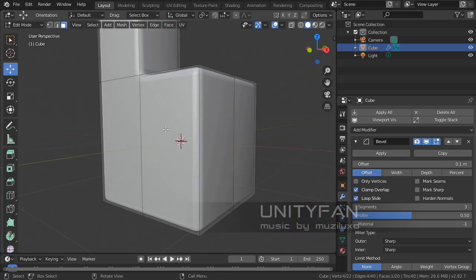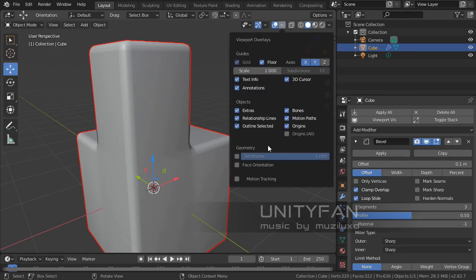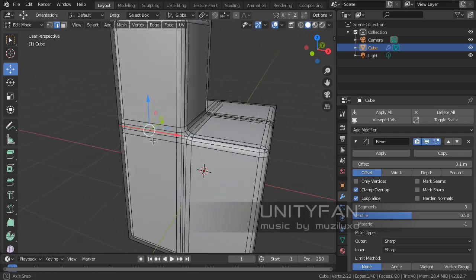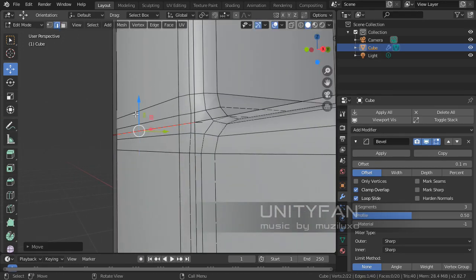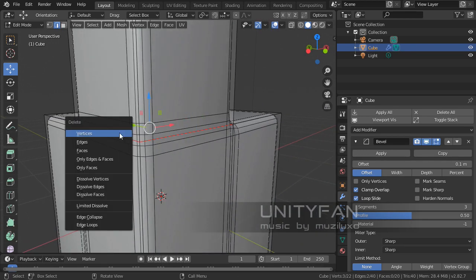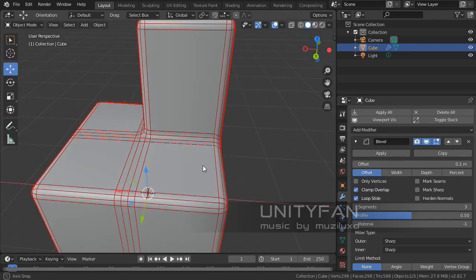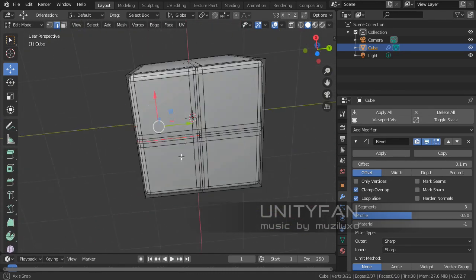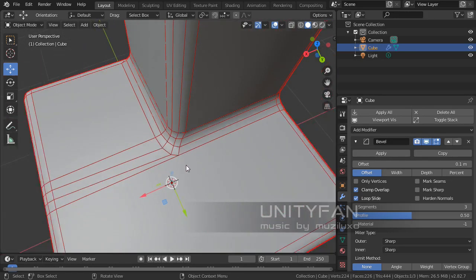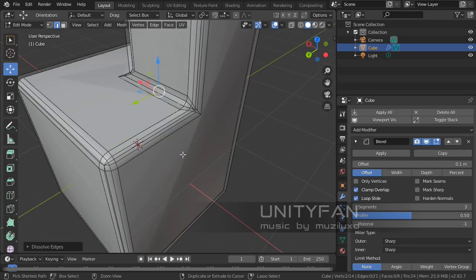But it can be achieved only on relatively simple geometry. With complex geometry you have to pay attention. Let me turn on wireframes for a second. It adds bevels to all edges, to all polygons. You see how here it's added 4 edges, and if we try to dissolve them, well, we can actually get, yeah, the results are actually good, I think. Actually, it's not that bad at all. But you can get stretches like this, or some weird geometry, so be careful and pay attention to it.